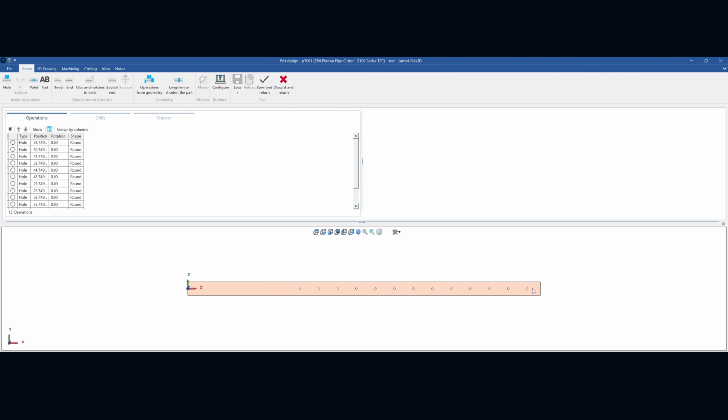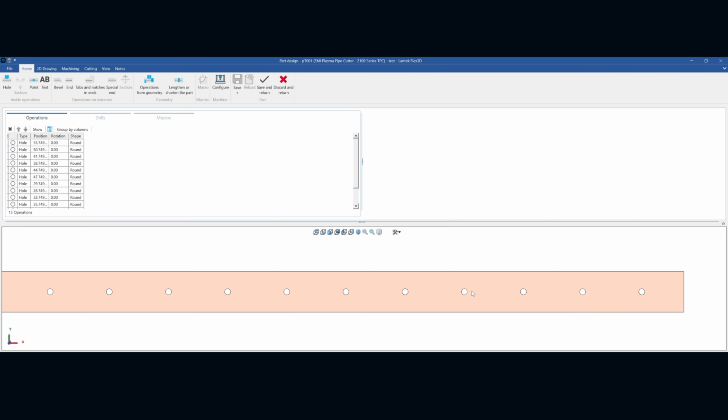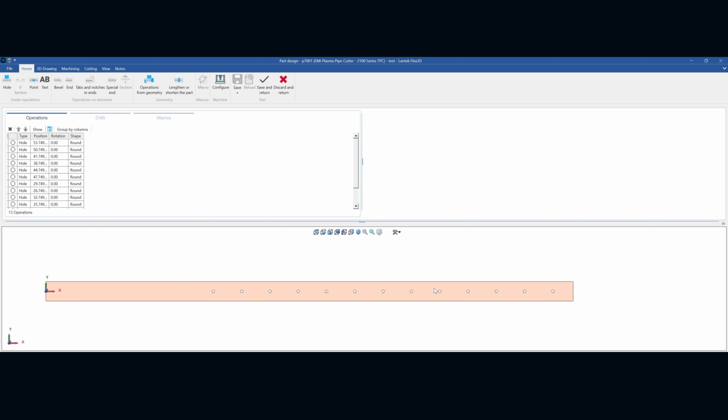It is a 1/2 inch flat bar, and these holes are 5/16 of an inch. If these holes were cut with plasma, taper would occur towards the bottom, preventing a bolt from passing through. Instead, the required operation is to drill these holes, which necessitates a center mark.